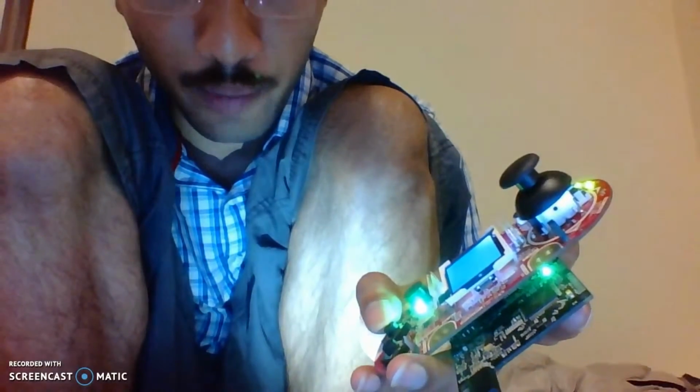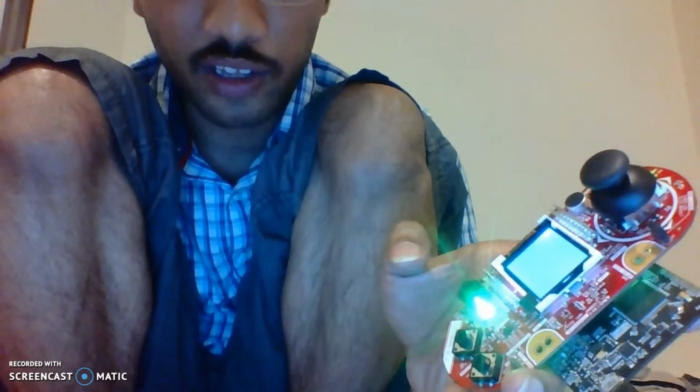Now let me present the priority of burglar and fire alarm over the doorbell. Hello, hello, hello. Now you see, even when the doorbell is being emulated, if I make a sound that is greater than the threshold, the burglar alarm is emulated. Let me now show you the priority of fire alarm over the doorbell. Let's press the doorbell and bring the mobile phone near it just after I press the doorbell. Now you hear that. For the first 2 seconds, we heard the doorbell, and after that, we heard the fire alarm. That's because the fire alarm is a higher priority.